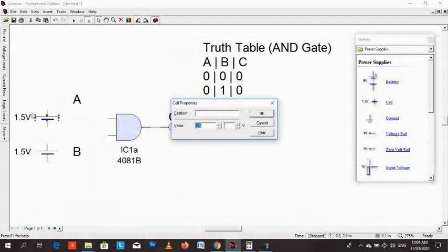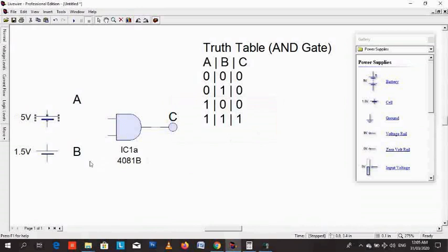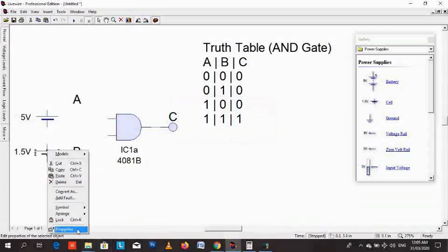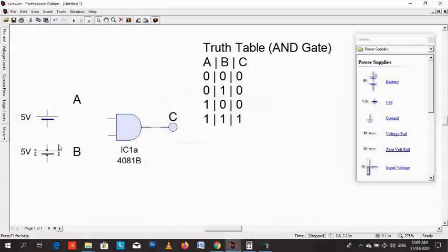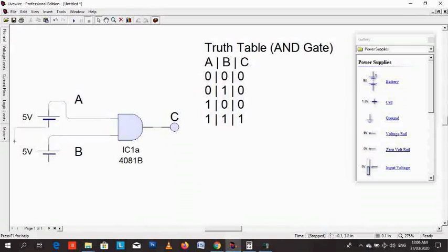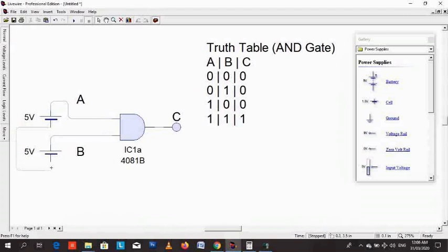Change the property. We want to change the voltage. We've said that logic 1 is 5 volts, not 9 volts. So we create our own 5 volts. Right click, change the properties, 5. So we've created two DC voltage sources, which will serve as our digital signals. You connect one end to one terminal: click and drag, click, click. To make a curve, you click again, and connect.